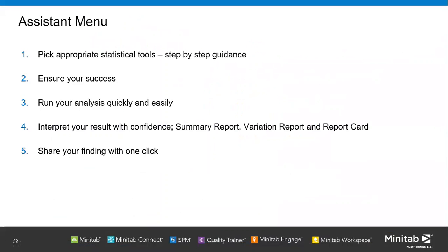So we have another way to get the DOE in the Minitab. We can use the Assistant, but with the Assistant, we have a limitation. If let's say you have more than 5 factors, you are not able to use the DOE in Assistant. So you need to go back to the DOE in the Stat menu. Okay, so that's why I always suggest you try with the Stat menu first, and then if let's say just only to reconfirm, just only to study, you might use the Assistant menu.